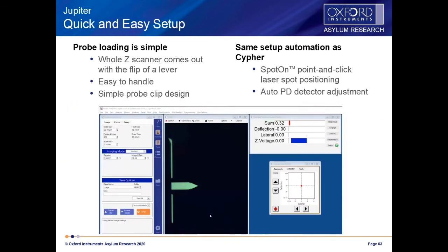The other nice thing is the instrument is easy to learn and easy to set up. There are several steps in doing an AFM measurement, and one of the steps is called laser alignment. Laser alignment means that if you have an AFM probe, you need to make sure that you put the laser that is required for doing the measurement at the right place on the cantilever. In most conventional AFMs, there are several knobs that allow you to align the laser. The good news is that UT Dallas selected a very nice instrument where the laser alignment is automated, so your life is going to be easier.